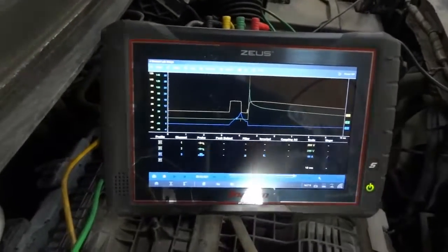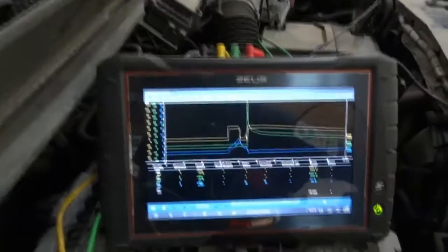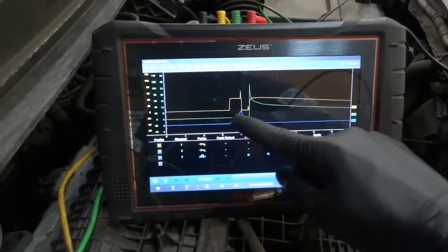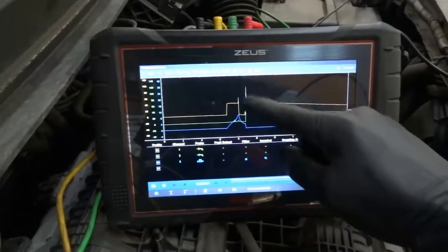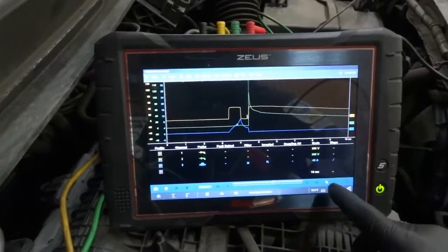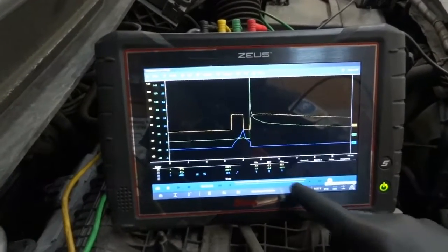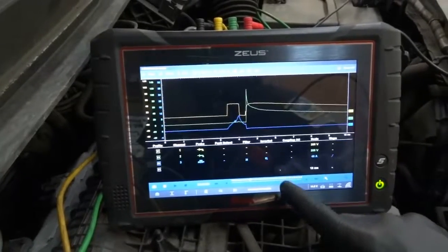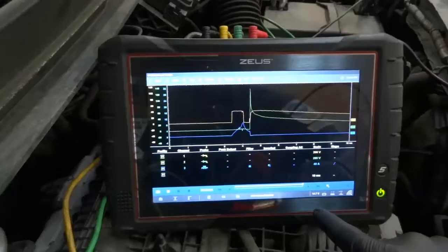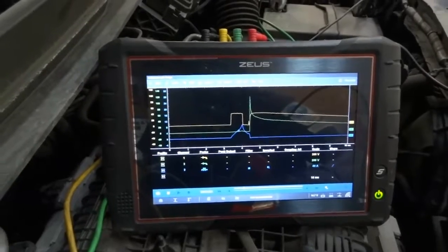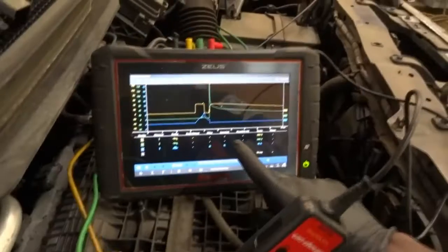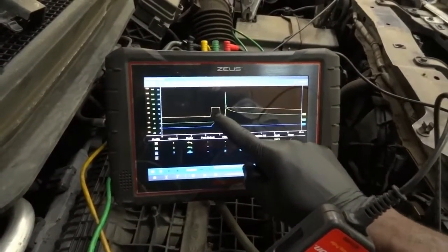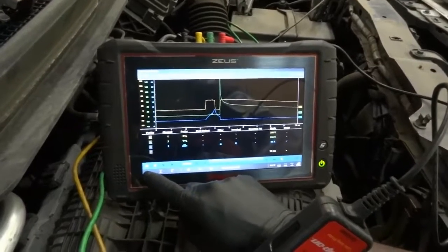As you can see, there isn't a big difference from what we just saw. Okay, so our current waveform looks pretty decent. Our voltage waveform looks decent as well. So the peak on the voltage waveform, so the green trace, the peak is 197 volt. Okay, and these are direct injection injectors, so these injectors spike a high voltage. And right now this waveform looks the same as the one we just saw.